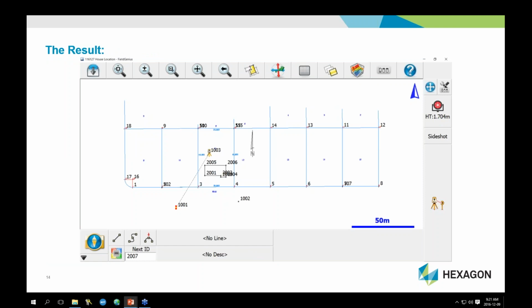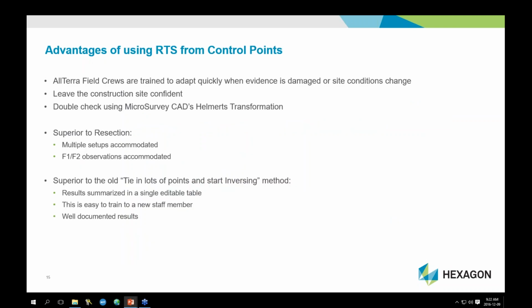So now once we've completed the calculation, you'll see that the field survey points are all adjusted and aligned with the plan information. And that calculation is done, and we've seen how well that should fit. So if you went in and inverse between each pair, you'd find that distances match what we saw in the calculation, and you'd find that that point, I think it was 507 down to the east. Sorry, no, it was 515. Yeah, you'd find 515 to 15 to be out by about 15 centimeters. So different cases we can use that tool.